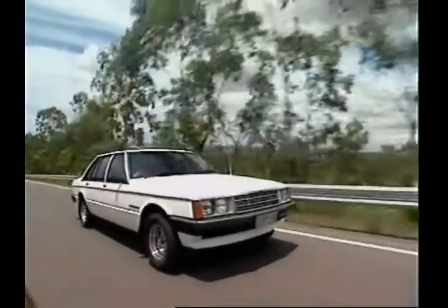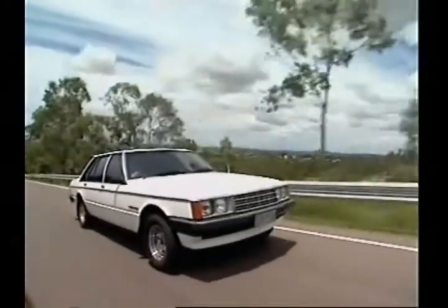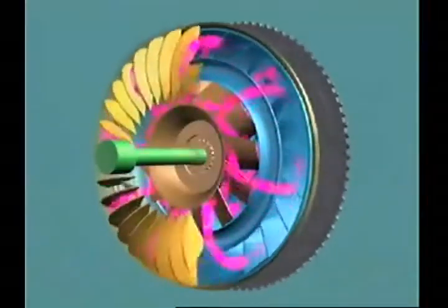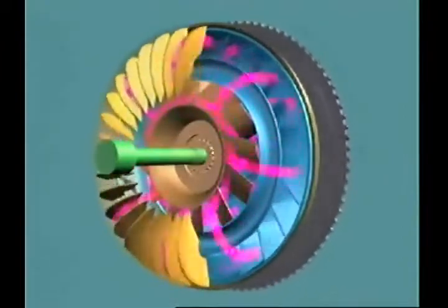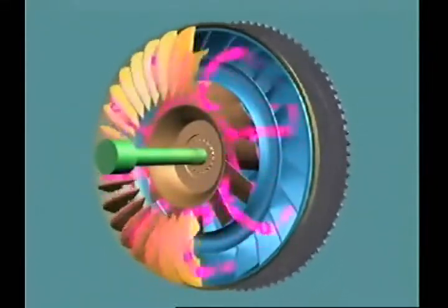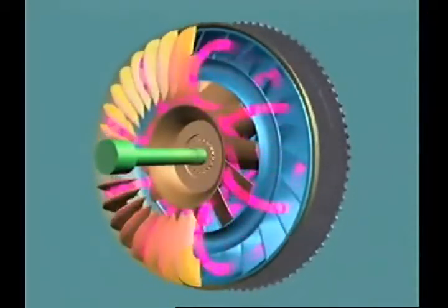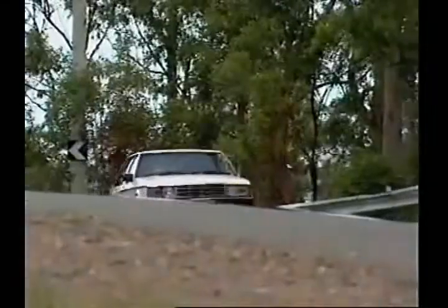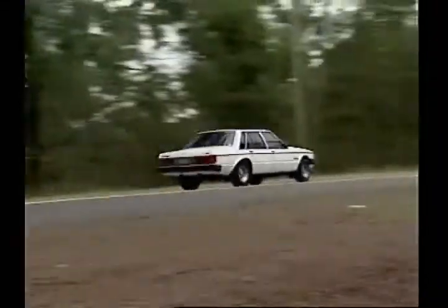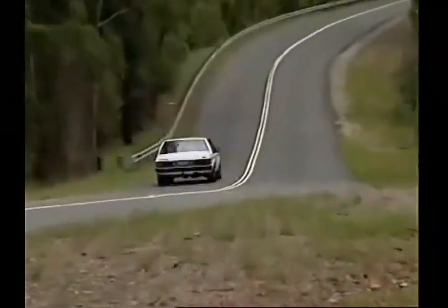During acceleration or hill climbing, torque needed by the drive shaft can exceed the engine output torque. As a result, the turbine slows, causing an increase in vortex flow. This again causes torque multiplication. The converter automatically adjusts its output within design limits to meet drive shaft requirements.